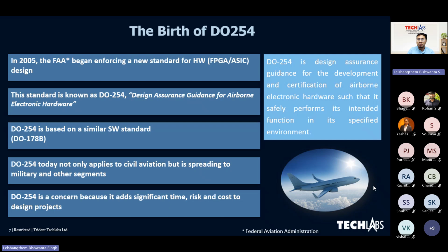Both AC and AMC 20-152A keep DO-254 at the core and add clarified objectives for custom devices, commercially off-the-shelf IPs and devices, and circuit board assemblies, extending the same assurance discipline to today's most complex hardware. Later in this session, for whatever discussion we have, we are taking reference from RTCA DO-254, the EASA and FAA's AC or AMC 20-152A, and the Airworthiness Directive.